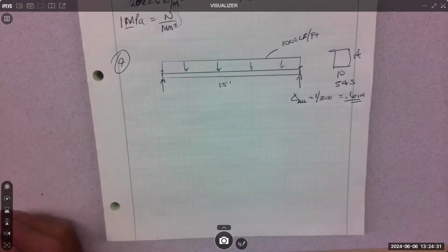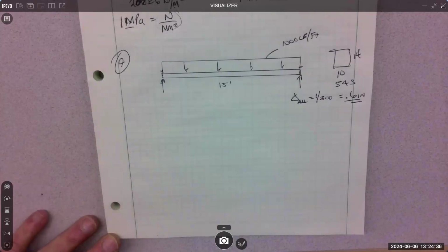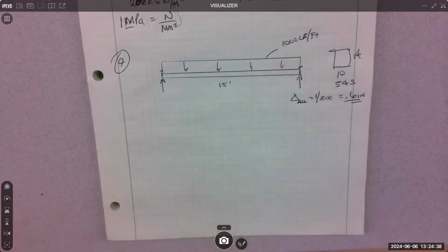On the final, we'll want to calculate the bending stress first, but we're just gonna do deflection right now. On the final, I will say, check it in stress first. That means check the bending stress before you calculate a deflection, because if it's over the bending stress limit, there's no reason to do the deflection, it's pointless. We're not doing that, because we're in academia right now, just calculating deflection. All right. What else is there?